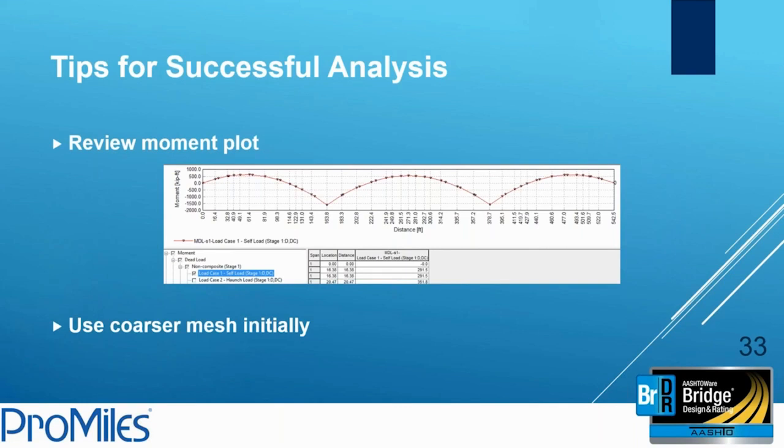Also use a coarser mesh initially, which will let your analysis run faster. Coarser mesh also means lower degrees of freedom, so your analysis will run faster.